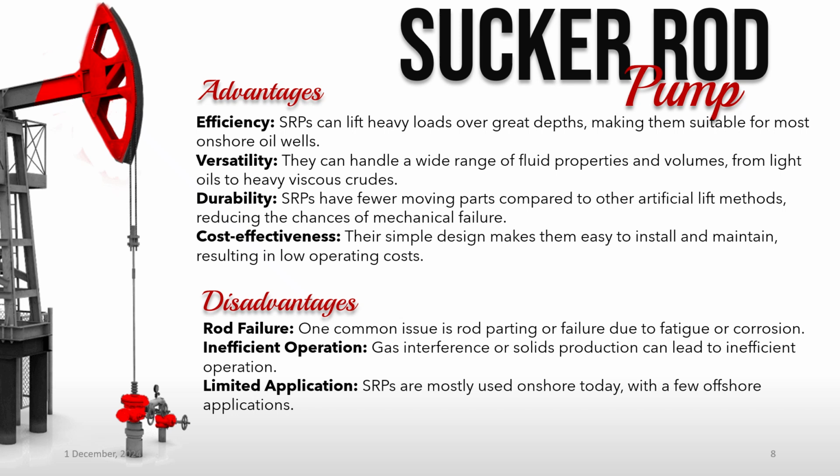Limited application. While highly effective onshore, the application of sucker rod pumps is somewhat limited in offshore environments. Their large surface footprint and the dynamic nature of offshore platforms often make other artificial lift methods, such as electrical submersible pumps, ESPs, more practical for offshore operations. However, there are still some niche offshore applications where SRPs are utilized.